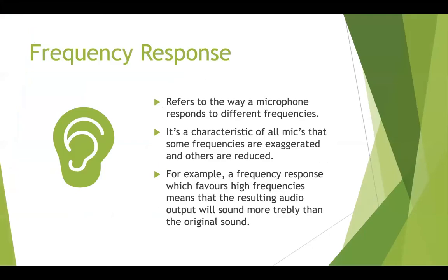Okay, frequency response. I talked a bit about it. I'll just go into a bit more detail. This is a frequency response when we talk about microphones. It's the way the microphone responds to different frequencies. Okay, it's a characteristic of all microphones. Some frequencies are exaggerated, some are reduced. You saw that before in the spec sheet. That Shure microphone had a boost in the 4,000, 7,000 range, right?